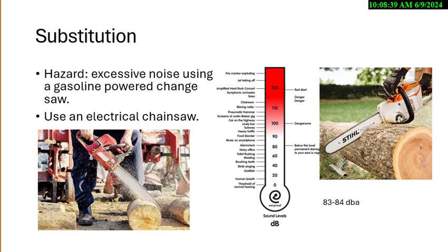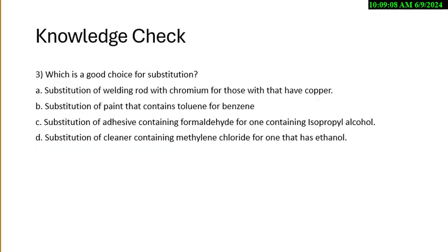Those are typical questions they'd also ask you. When you cut, it's going to make a little bit more noise. So we didn't really eliminate the noise hazard; we just brought it down dramatically. If we were below 80 decibels, then you could say we have eliminated the noise. But studies have shown that excessive exposure to 83, 85 decibels over 24 hours can cause hearing loss. So that's a substitution case, and that's a tougher one.